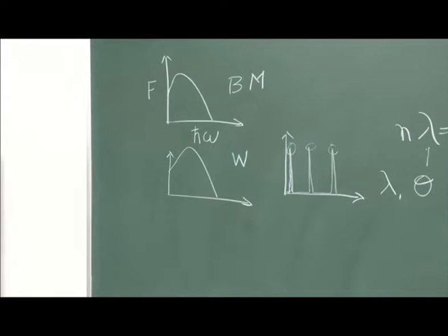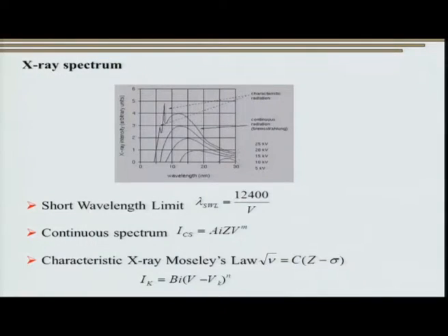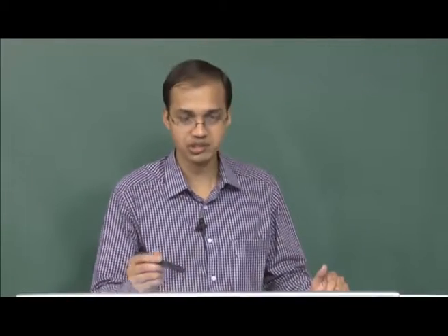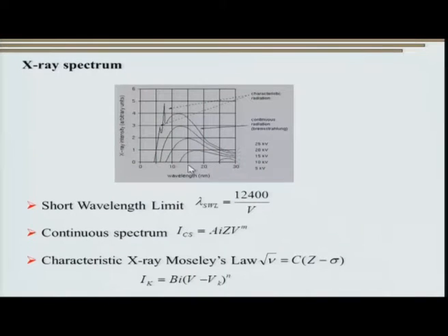So, now coming back to our normal X-ray diffraction, all of us know that as we increase the voltage, initially we get no intensity at all, which is essentially known as the short wavelength limit. If you look at this curve, this I am sure must be covered in your course on X-ray diffraction, but since this is an advanced course, I thought we will go through it again. We see that for a particular wavelength there is no intensity.